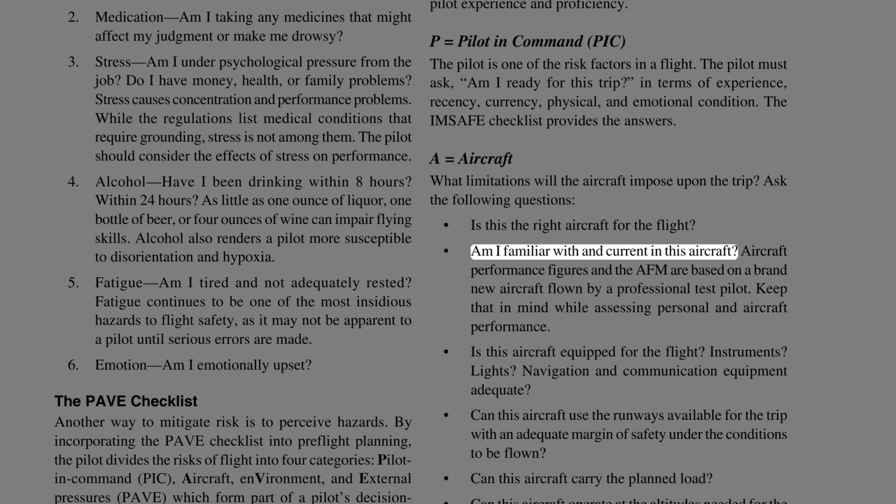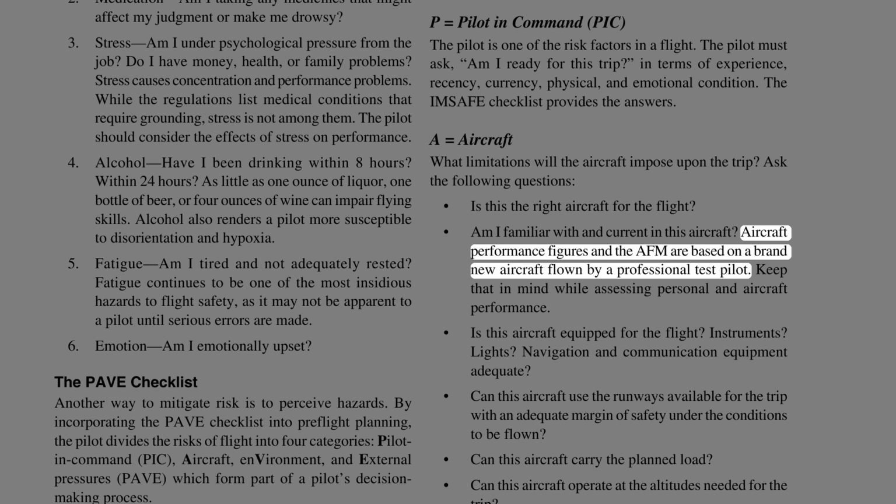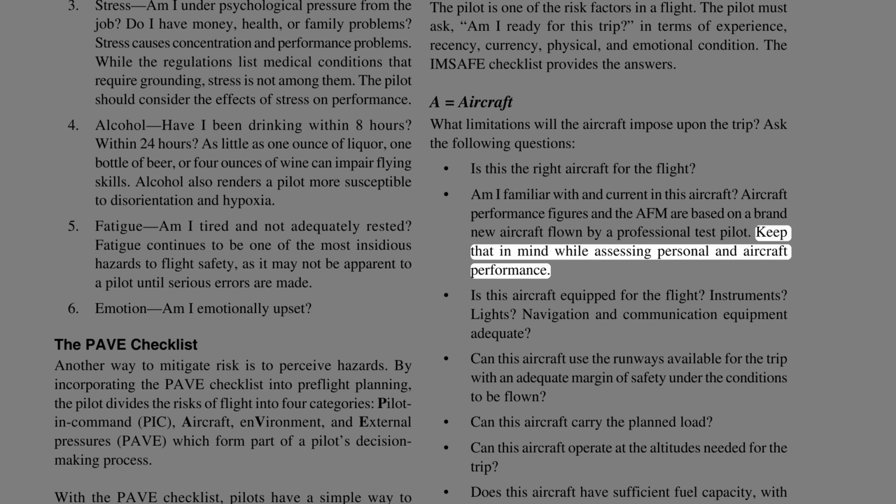Am I familiar with and current in this aircraft? Aircraft performance figures and the AFM are based on a brand new aircraft flown by a professional test pilot. Keep that in mind while assessing personal and aircraft performance.